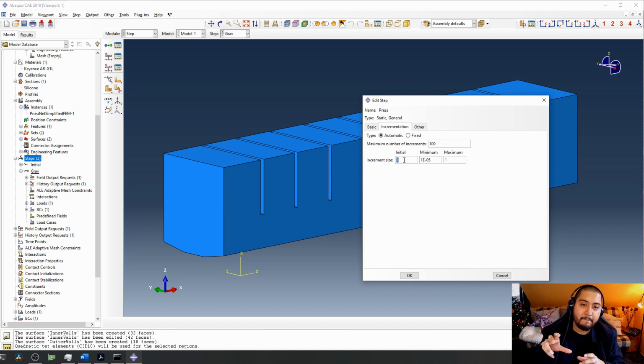1 second, it's going to try to simulate from this point, in which gravity is already applied, to the end, which is a lot. And even if we have a really small mesh, you cannot really compute the in-between steps, and the mesh is really highly deformed, and the elements are going to be highly distorted if we have a huge step. So I really recommend a step of probably 0.001. If you can compute this, then this is a good minimum value.